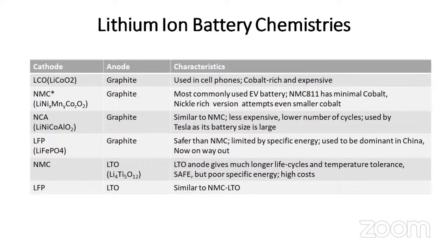That event is called thermal runaway. In this type of cell, LTO and all, they have high temperature tolerance and are not that sensitive to heat compared to NMC and NCA. So these kinds of cells are somewhat safer than other cells.